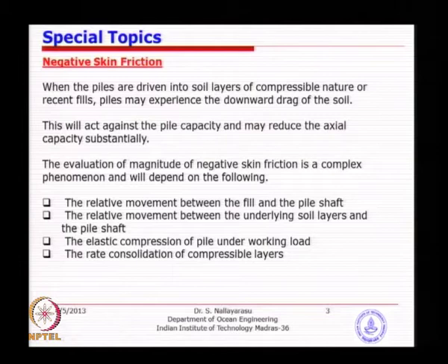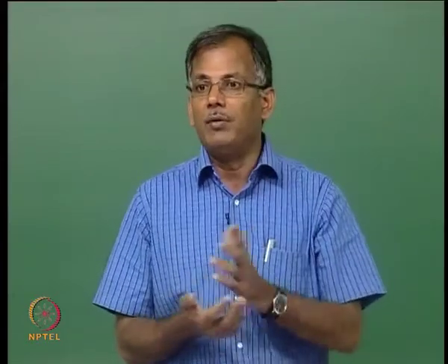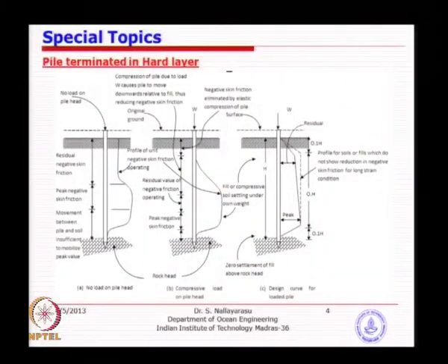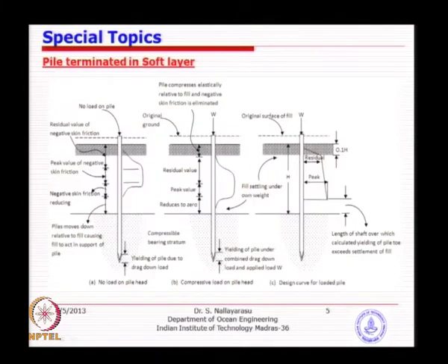If you install a pile of 20 meters in a coastal area and make sure that the pile is going to be end bearing, your assumption of loading may be 100 tons and you provide a 100 ton capacity, but if the soil layers compress and displace, the additional load can be several times higher than the actual load of 100 tons. So, the pile will immediately fail because of this kind of problem, because the pile will start yielding at the base, because the soil layers also add to the load. Some piles have failed like that, and in fact some structures have collapsed because of this kind of phenomenon on constructed fill. Of course, this problem is not so much for offshore as I mentioned earlier, but still just to understand what the problem is if you have a top layer settlement. So, you need to just understand this fact.